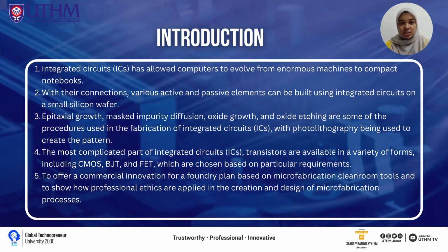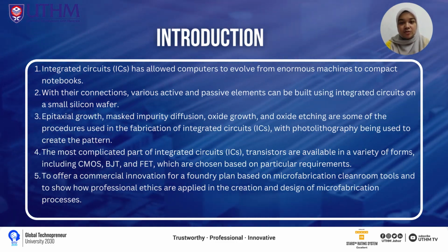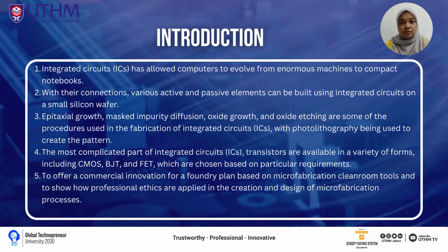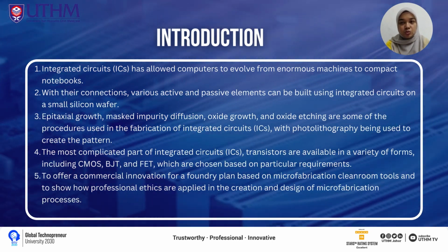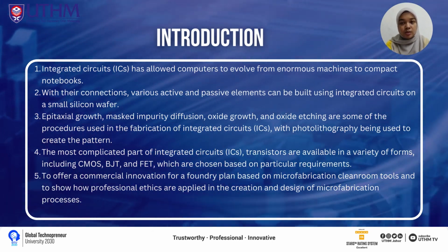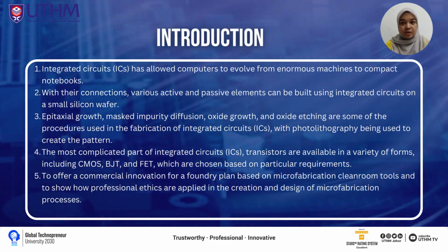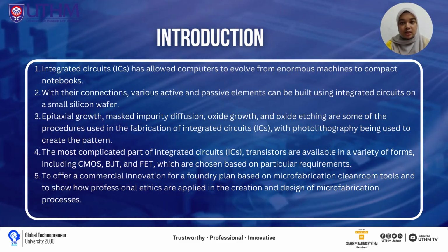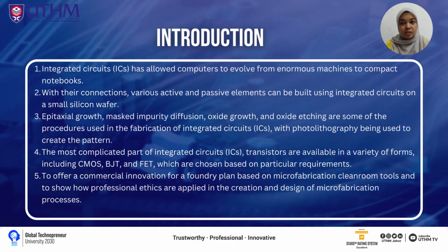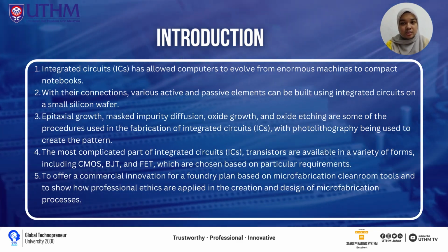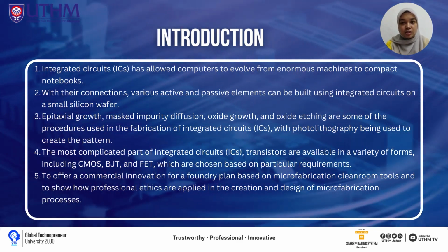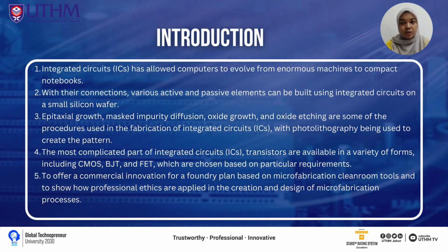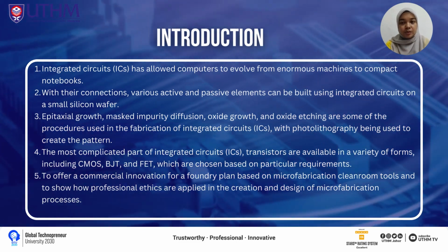So today for the introduction to this project, the first one is the invention of the integrated circuit, IC, which has allowed computers to evolve from enormous machines to compact notebooks. Second, with their connection, various active and passive elements can be put using integrated circuits on a small silicon wafer. Third, epitaxial growth, masking, impurity diffusion, oxide growth, and oxide etching are some of the procedures used in the fabrication of integrated circuits, with photolithography being used to create the patterns.